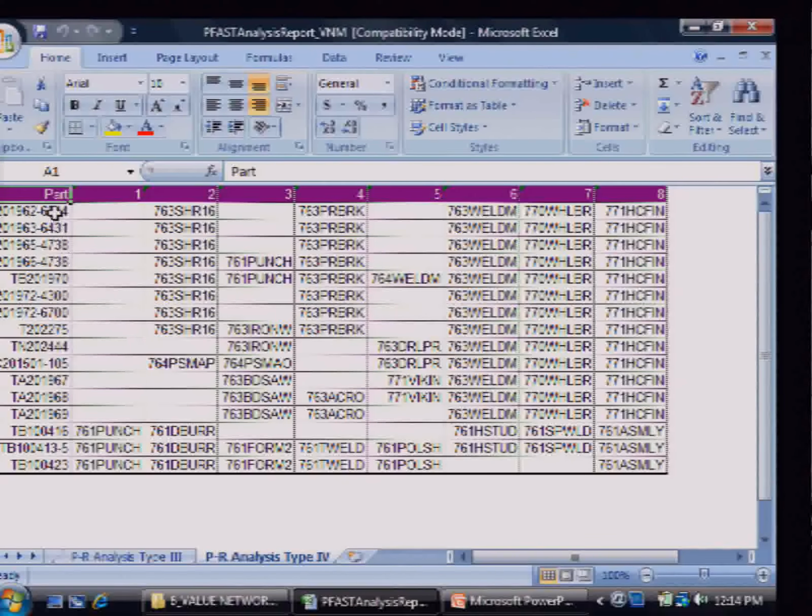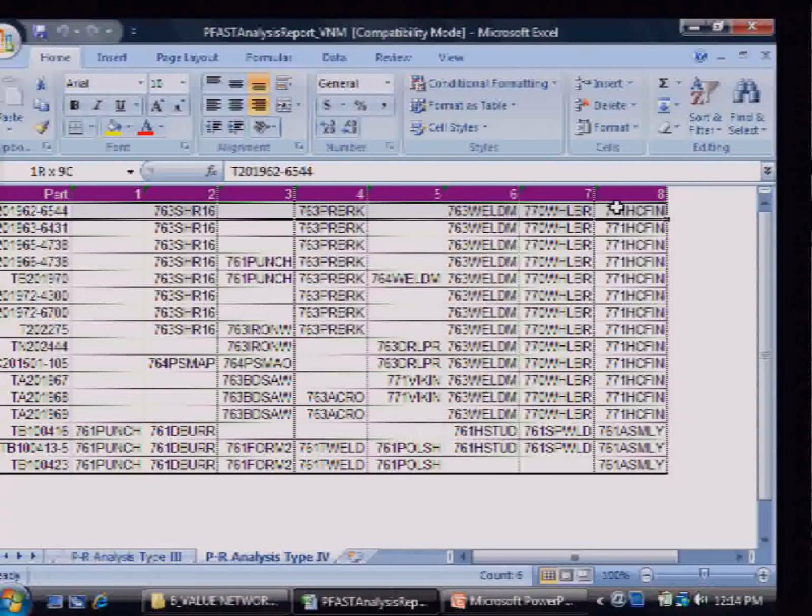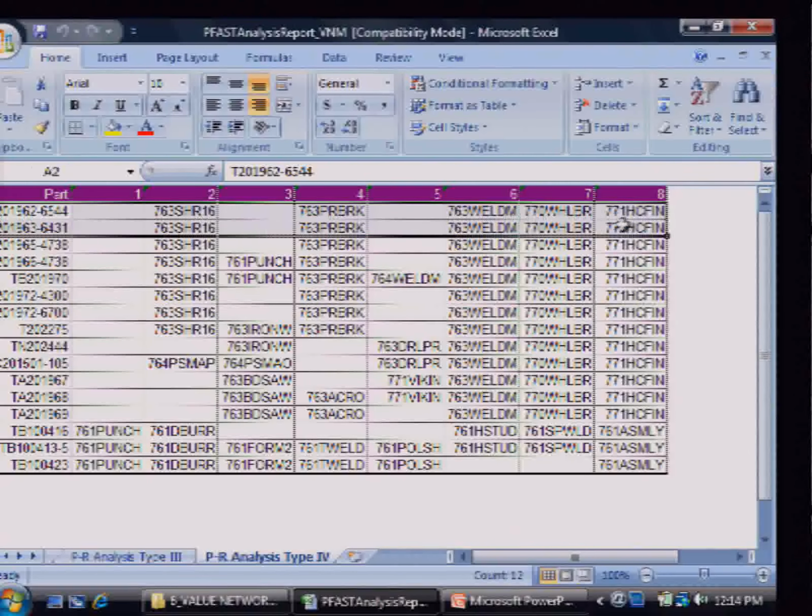in PR4, what we are doing is putting one beneath the other those value streams which, if you put their equipment in that logical sequence, pretty much all the products would flow from the left end of the facility to the right end, or the top of the facility to the bottom. So even a job shop could physically, viewed from the rooftop, be made to look like a Toyota assembly line where everything is going from one end of the facility to the other end. So what PR4 does is it puts one beneath the other those value streams which are identical or very similar in the logical flow of products from operation 10 to the last operation.